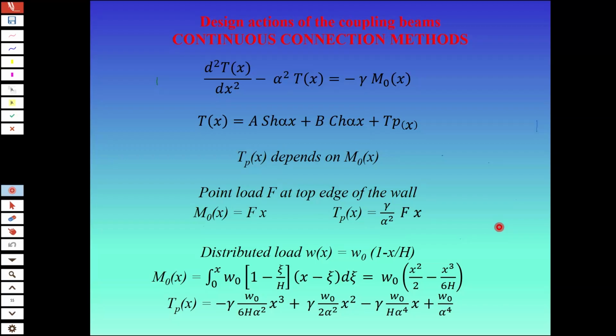Why is that beam overstressed? Well, probably I can put a little bit more reinforcement there. So this will help you also to control these red points with red colors, which will come out of the software. So the software analysis is really the very last check.